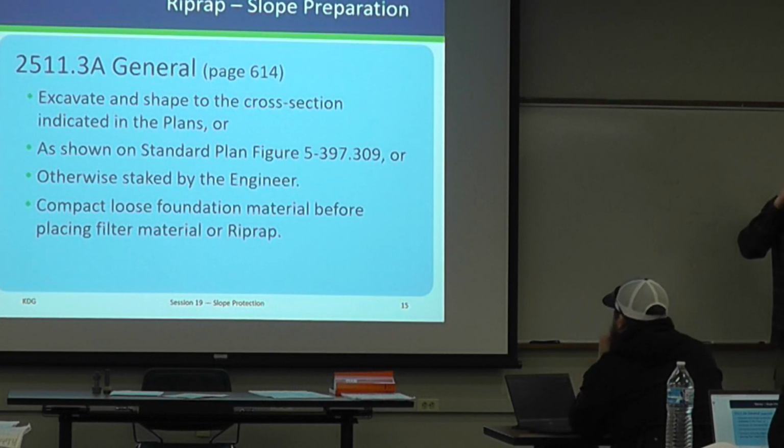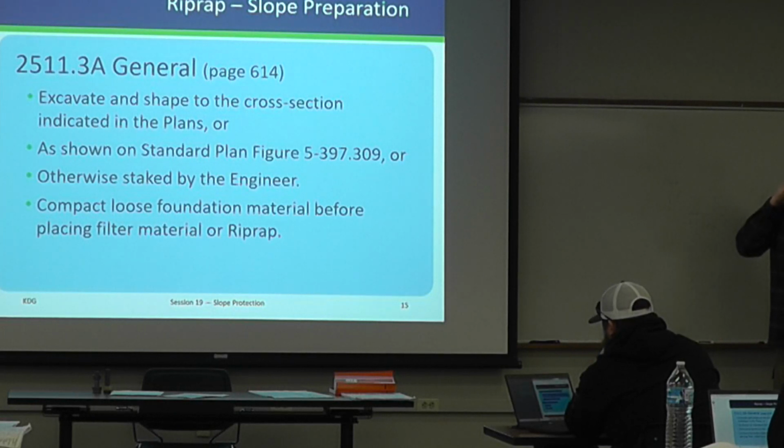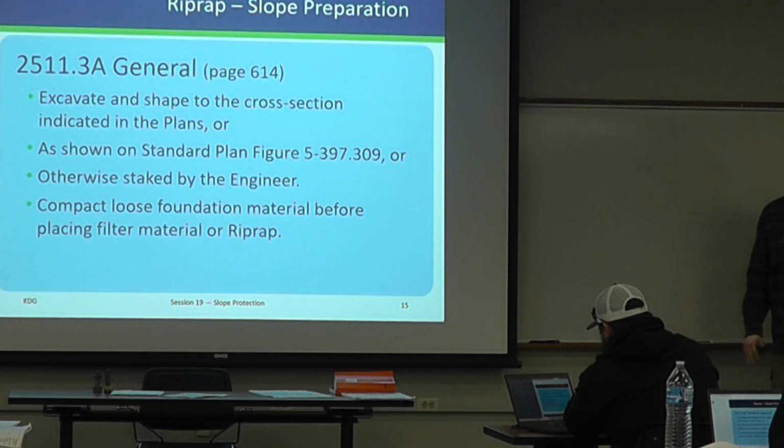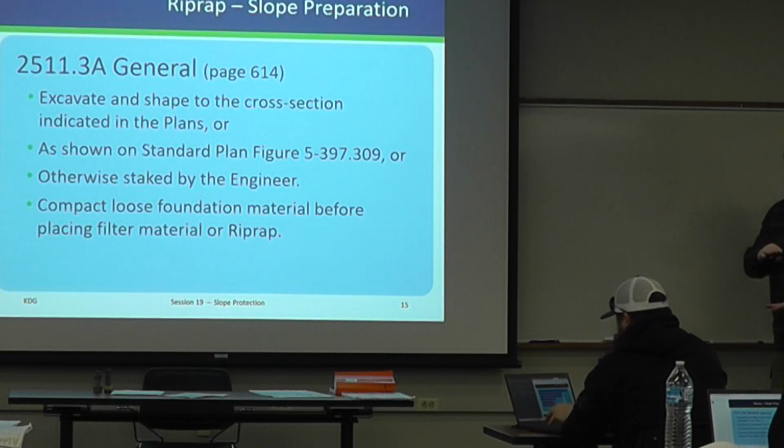So before you place the riprap, just like creating a roadway, you gotta prepare the base, right? So we're doing the same thing when it comes to riprap. We don't want to just leave high spots and low spots. We want a nice uniform base to place the riprap on so that when we place it, we have a uniform thickness.